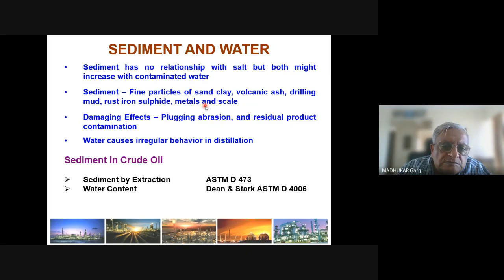Those tanks are used to settle the crude. We settle it for at least a week or so, and then the BS&W gets precipitated down. The particles, the water and the salt, that sludge, gets precipitated down, and we remove it.